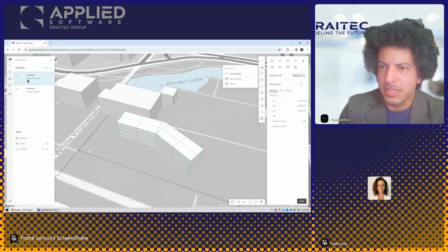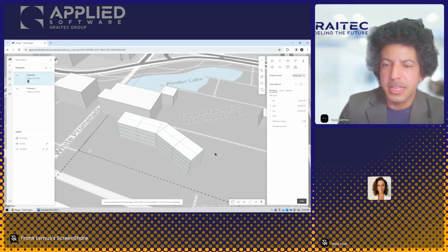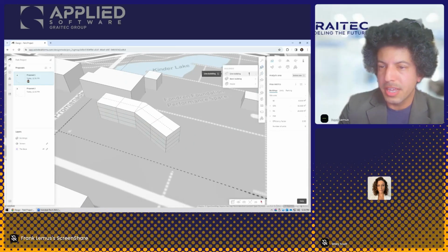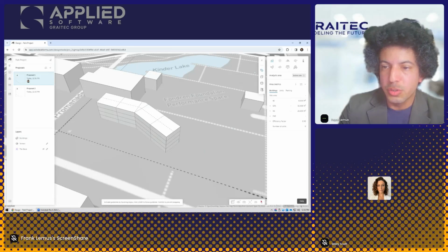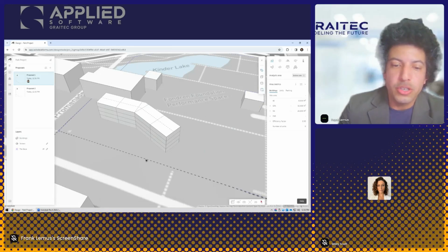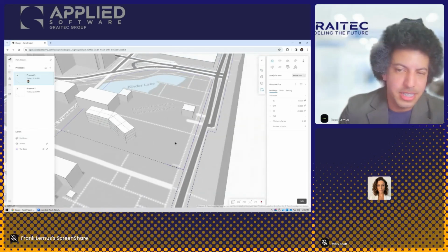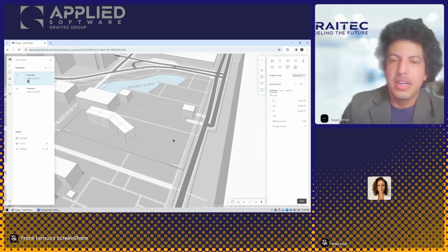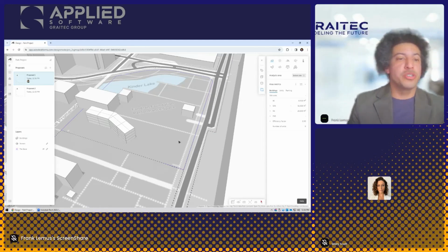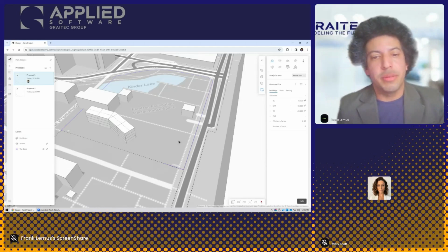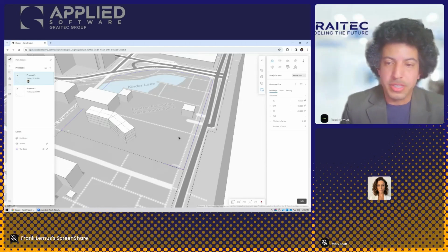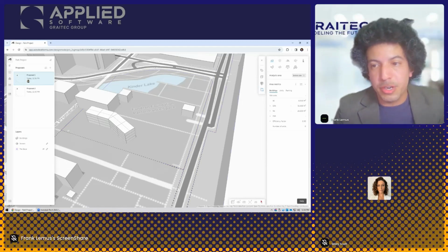So this is me creating a building based on line. If I go over here and say basic building, see the shortcut B, then it takes me to these tools right here. You can select an element that already exists. Now you wouldn't use this here because it's selecting elements like the boundary lines. That's not practical. You would be selecting something you would have imported yourself from AutoCAD, for example. Maybe you already have the footprint of the building. You could just click on that to select the footprint. It does require that you import that CAD file first.